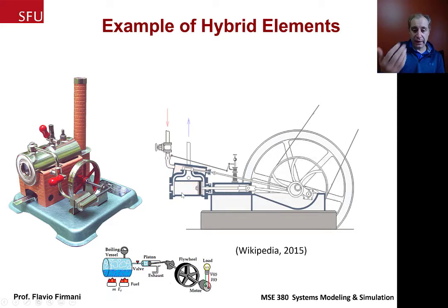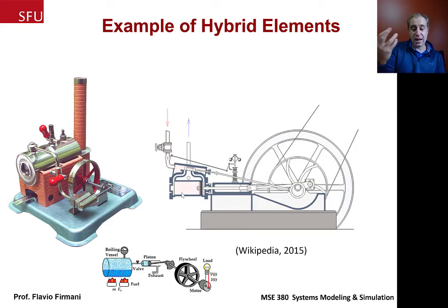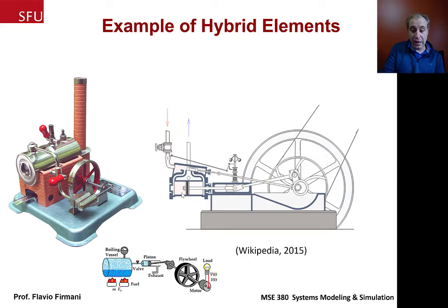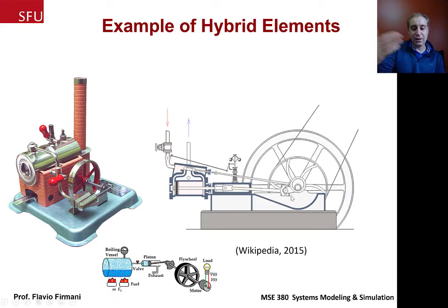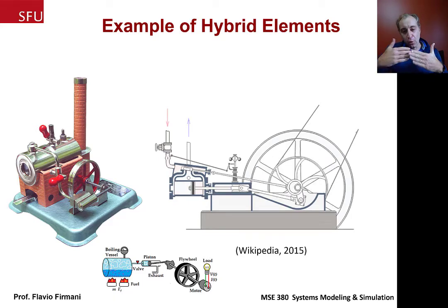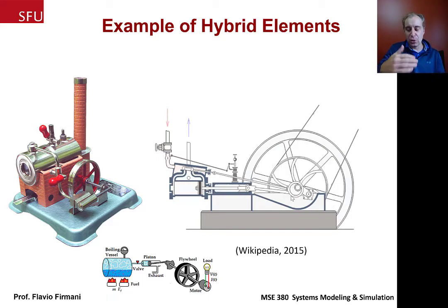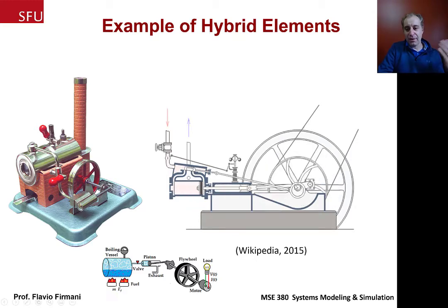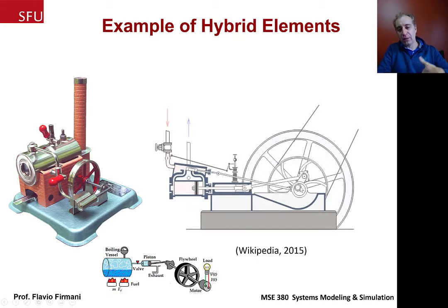And then we would apply the concept of pressure and force. There's going to be a relationship there that will produce the motion of the piston. Then the force that the piston is applying to the crank is going to be related to the moment or the torque that we're applying to the flywheel.